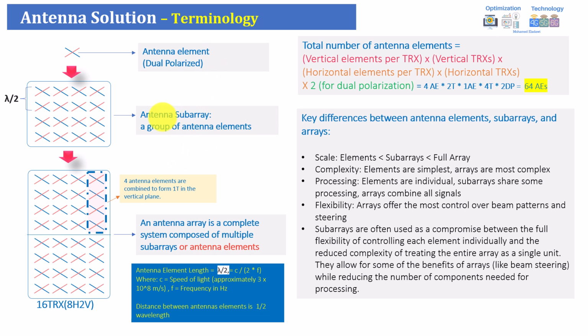Okay, here there is a very, very important terminology. If you really understand it, you will understand how massive MIMO or the active antenna in general improves the performance in MIMO and beamforming, which we're going to discuss in detail in the next sessions. As you can see in the left figure, this is showing three figures. The first one is a very small unit, which is called the dual polarization, which we just highlighted in the previous slide. This dual polarization, for example, plus 45 and minus 45, is called dual slant polarization.